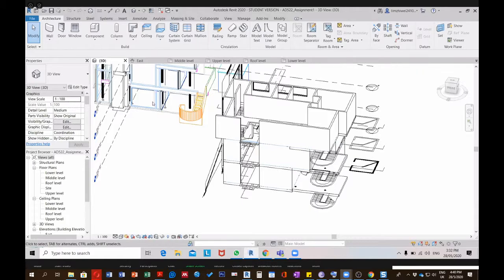And then if you click here, you will see the library of walls that you have. These are all the walls that already exist in the template of Revit. So these are many different types of walls. But we are interested only in this type, generic wall, and we need to change the thickness.